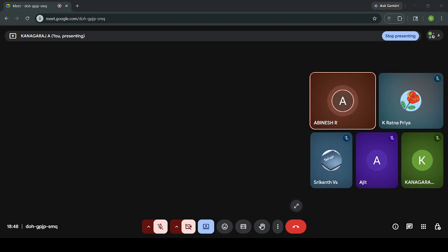Here, for the bottom right, SOT-223, there are three pins, but we also have a fourth pin at the top. For example, the bottom three pins are 1, 2, 3, and the other pin at the top also refers to 3 because it goes to the ground. Next one.